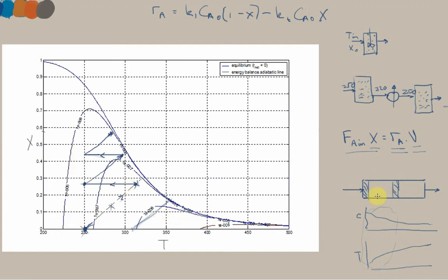So for the plug flow reactor and the CSTR, for the CSTR volume, we just look up that end of the line to get the volume. Whereas for the plug flow reactor, we can see we need to integrate along this line to find its overall volume. Anyway, we'll come back to the calculation of the reactor volumes a little later in the same lecture.